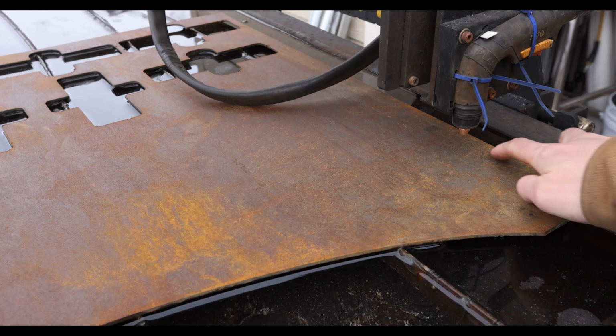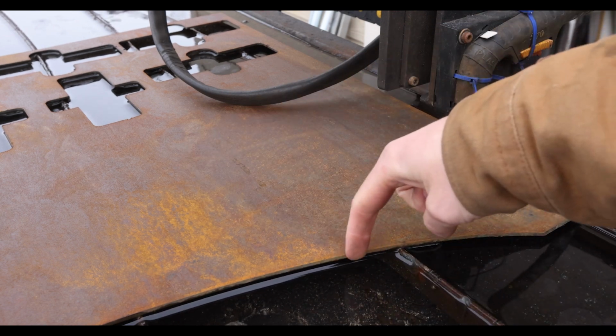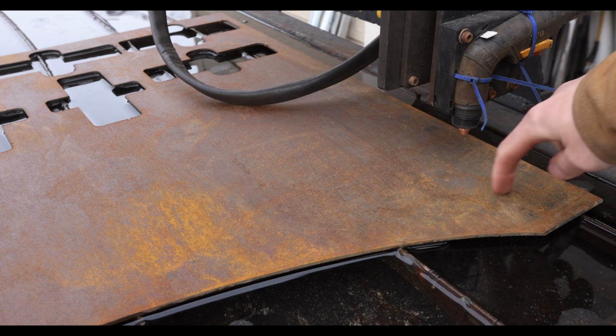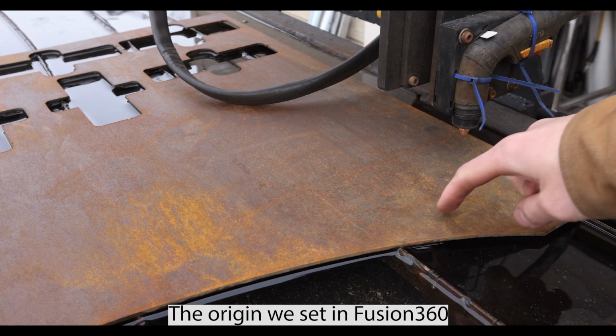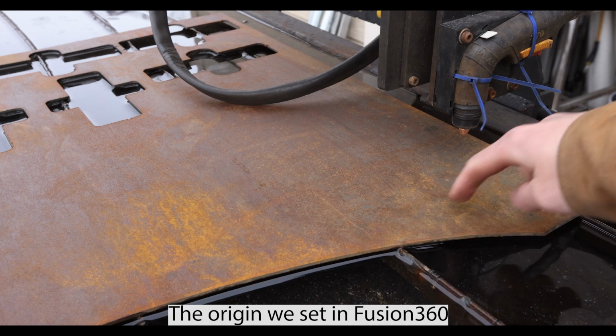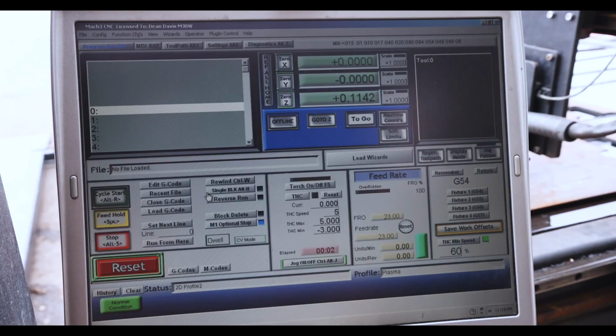So I want to cut the part right here. So I'm going to line it up where it just barely cuts up to this point and then goes over. So I need to first find the origin and zero that somewhere over here. So the way I'm going to do that is first by loading the part.